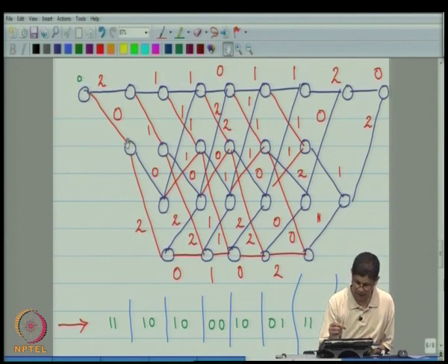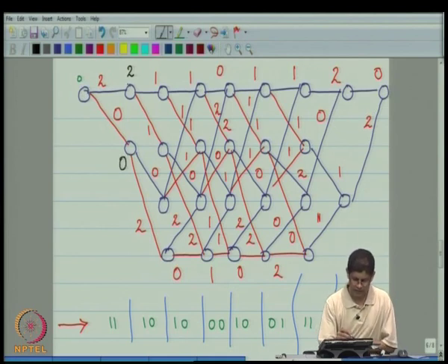Okay. So if you like, you can actually choose a different color to indicate branch metric, and maybe what should I choose? Let's see if yellow stands out. I guess it doesn't. Maybe I should use black. How about black? So this one is 2 and this one is 0. Now I am attaching the branch metric to the nodes, just so that I know that the path leading to this node has higher Hamming distance than the path leading to this node.